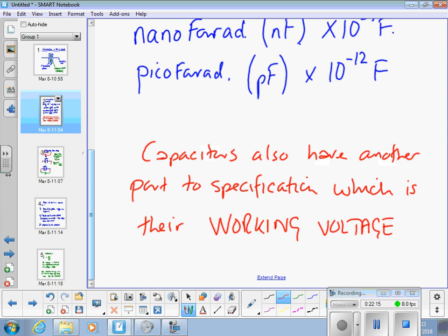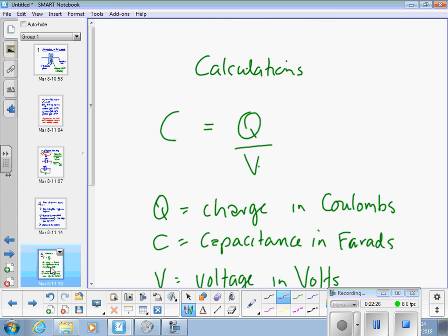So talking about this constant current being applied, keep applying that 3 amps, the charge keeps going up. If we look at the other formula, V here would be charge divided by C. So the voltage is going to keep increasing and increasing. Eventually, we go over the working voltage of the capacitor.